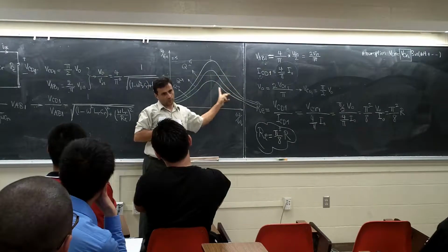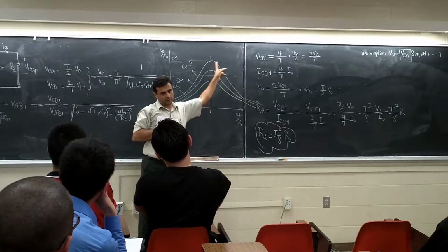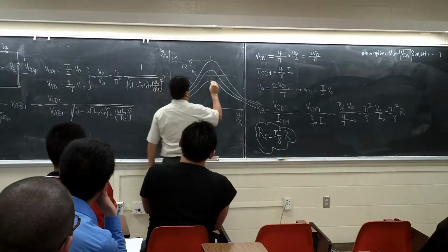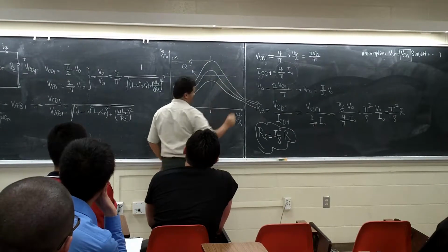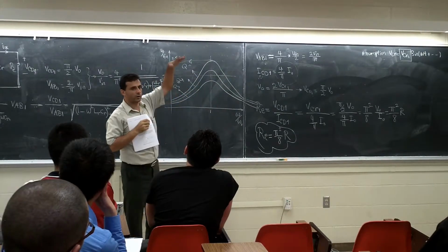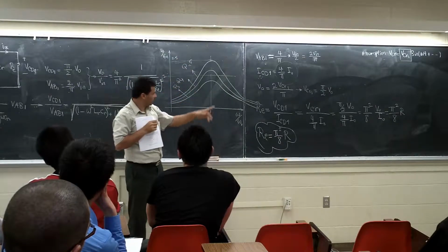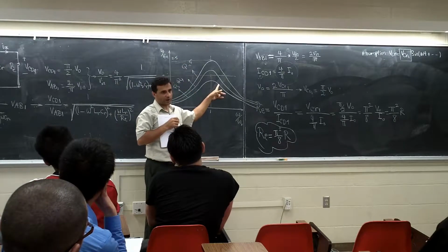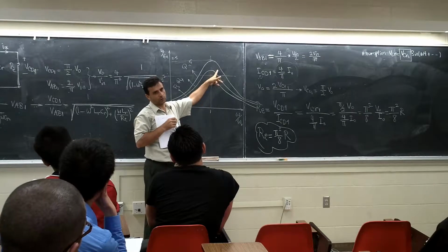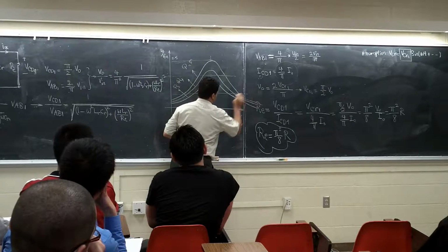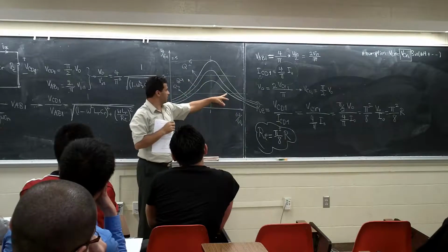You said we are going to work for omegas more than resonant frequency, right? We are going to be here. So basically, this is what you need to define: what kind of load you have, how much your load is going to vary. For example, if your load comes to this line, we cannot provide 2 times the V in, right? So somewhere here would be the answer. This is the minimum Q I'm going to have.